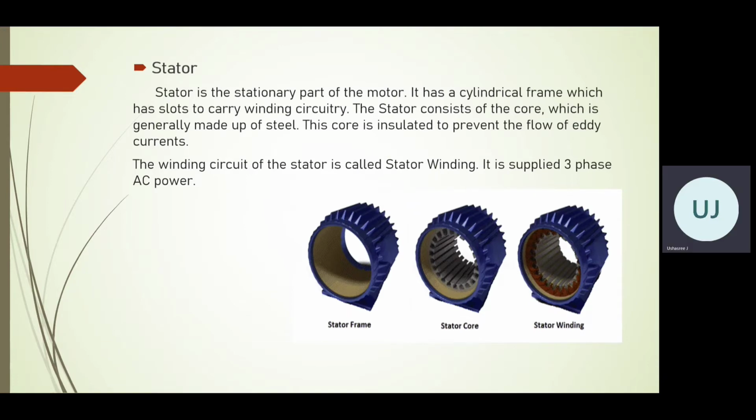Stator. Stator is the stationary part of this motor. It is constructed with thin silicon lamination and insulated by a surface coating, to minimize the eddy current. The winding circuit of the stator is called stator winding. It is supplied with three-phase AC power.